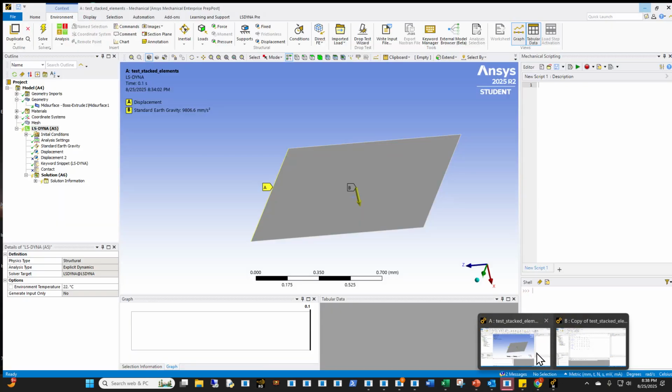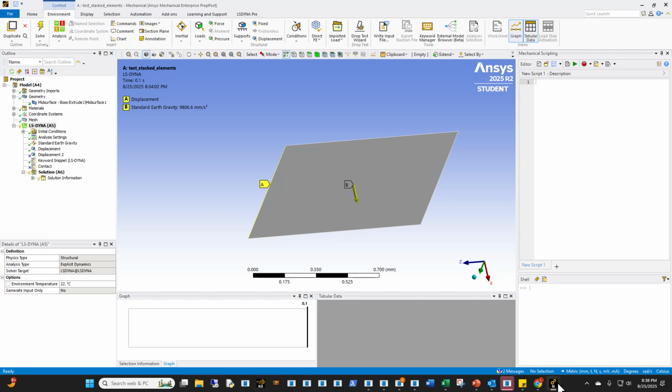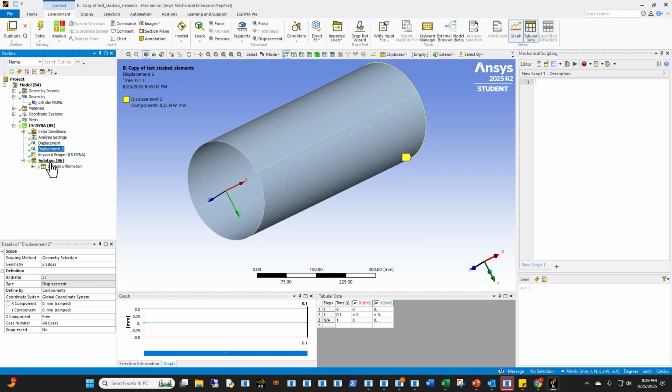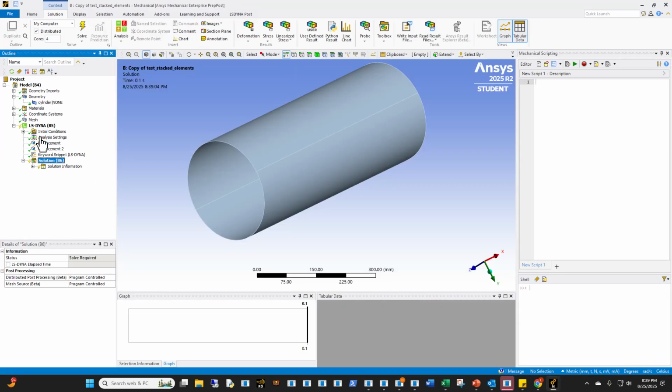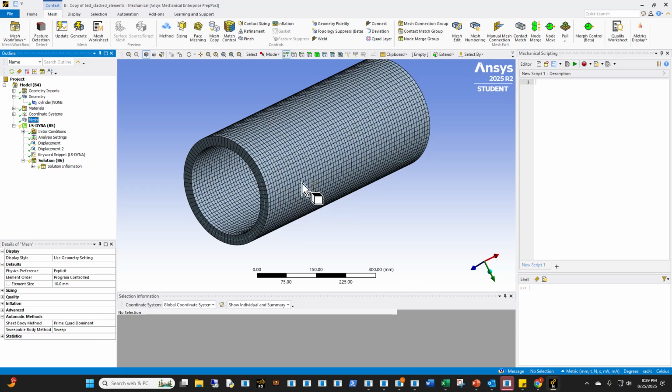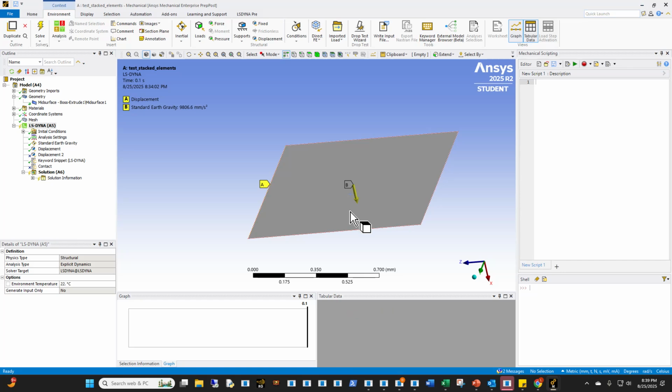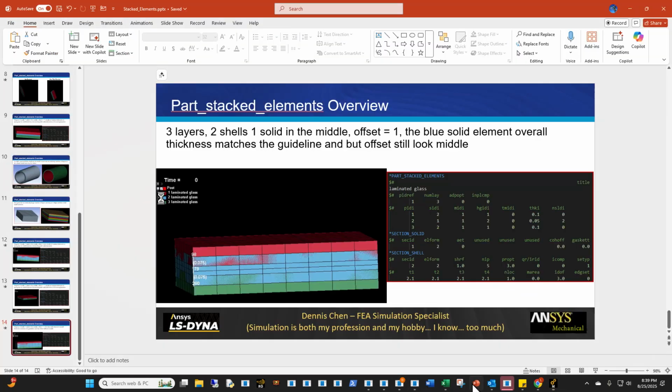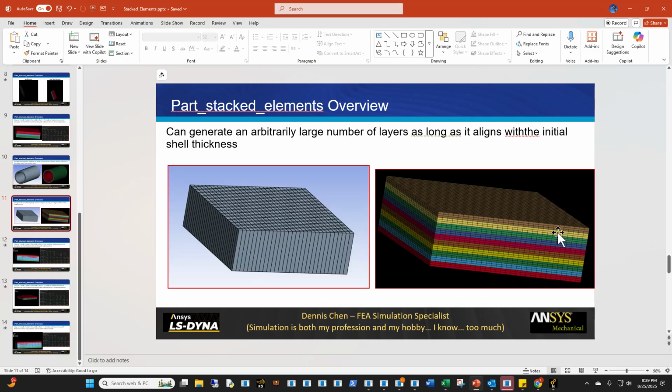So all I have to do is import one of these, and then do a basic setup. I have my keyword template imported here. This means nothing in here, but when I export this model, it's going to look like it has a single layer of elements. But when you start the LS-DYNA run, what's actually being processed, what's actually auto-generated, is the shell that you're seeing here. Shells like these are auto-generated at the start of the transient analysis.